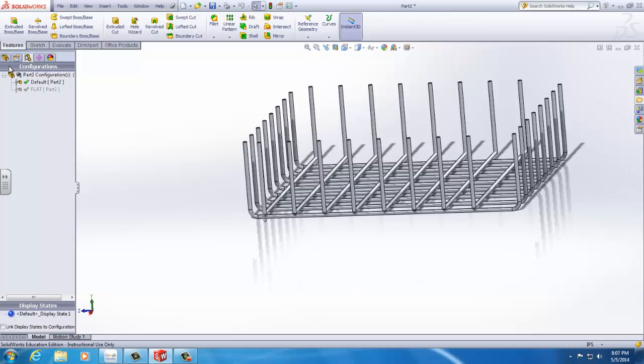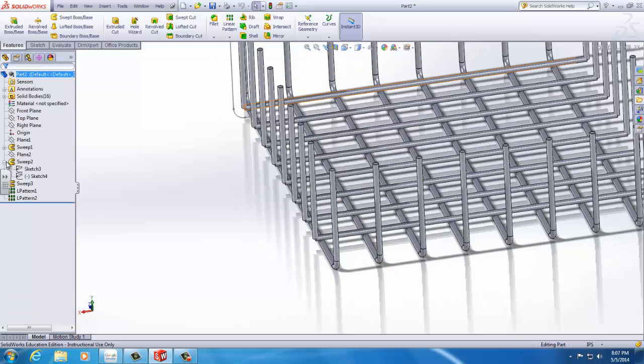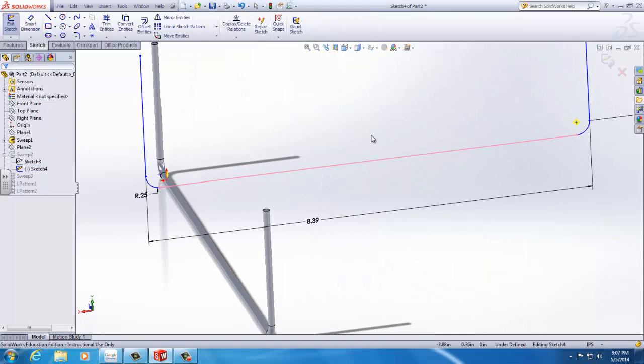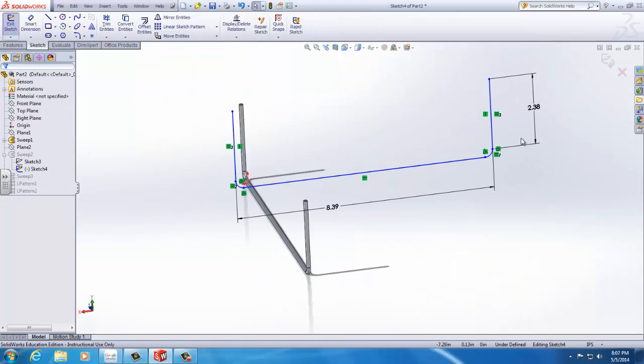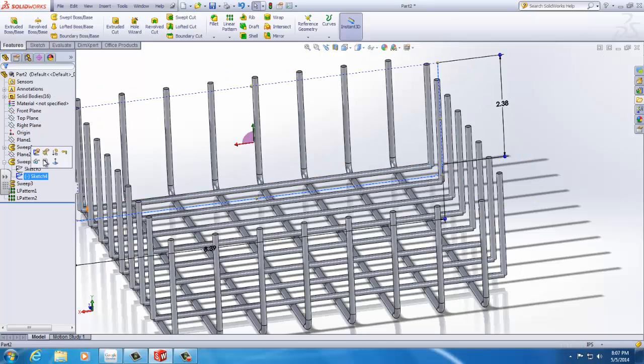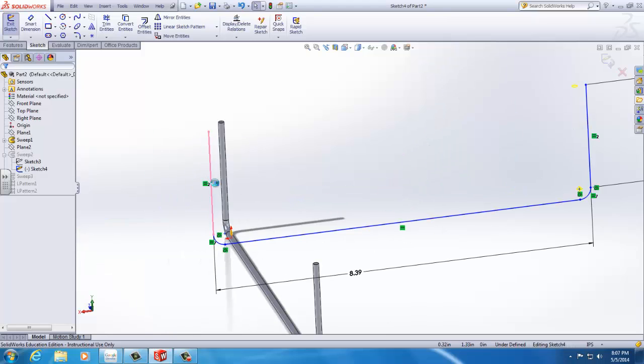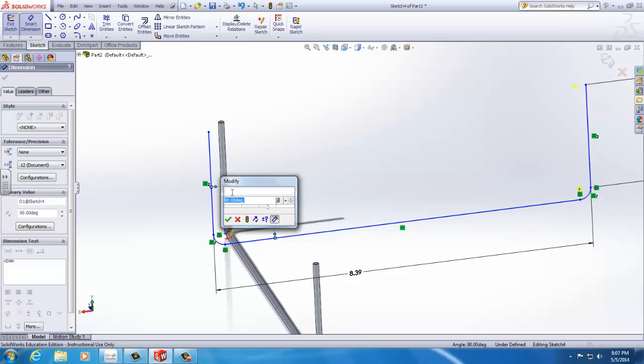You do the same thing with the other part. I need to give it a thickness. You guys don't have to do Tools, it's just Insert, Features, Thicken, for your own understanding. Select the surface object that I want to thicken. Again, it defaults to 0.1, which might be too much based on how big this drawing is. I'll give it a 90 degrees as a reference, very small.